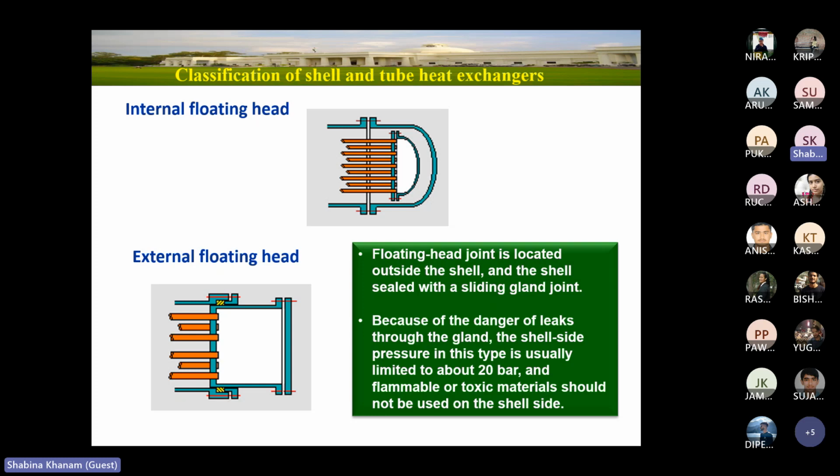If your fluid is toxic in nature, temperature is higher, fouling tendency is there, you can choose internal floating head.